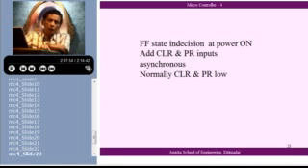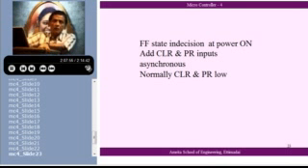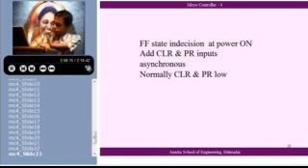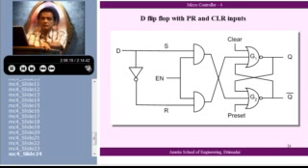In many cases you will find that when you work with the flip-flop, when you switch off the flip-flop and switch on, there can be an indecision. You don't know what state it will go in. To take care of that, your flip-flop will have additional inputs. These are called the clear and preset inputs. This will also be added to flip-flops. Normally they are called clear input and preset input. They will be added to the flip-flop separately and independent of the external enabled clock.